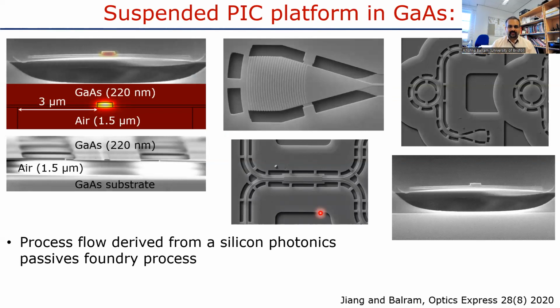To build these kinds of devices, it's important to keep in mind that these devices are quite sophisticated. So one of the first things we did at Bristol was to build a photonics platform that was capable of this kind of sophistication. And we chose to work with gallium arsenide for various reasons, the most important of which is that it has very good optical properties and reasonably good mechanical properties that are suitable for doing these kinds of transducers, in addition to possessing a weak piezoelectric coefficient, which, as I'll show, will be the main limitation.